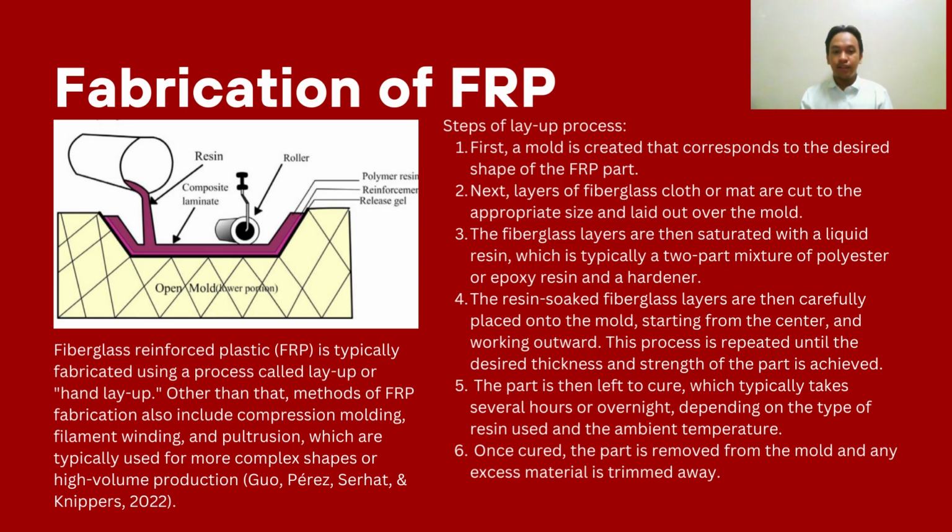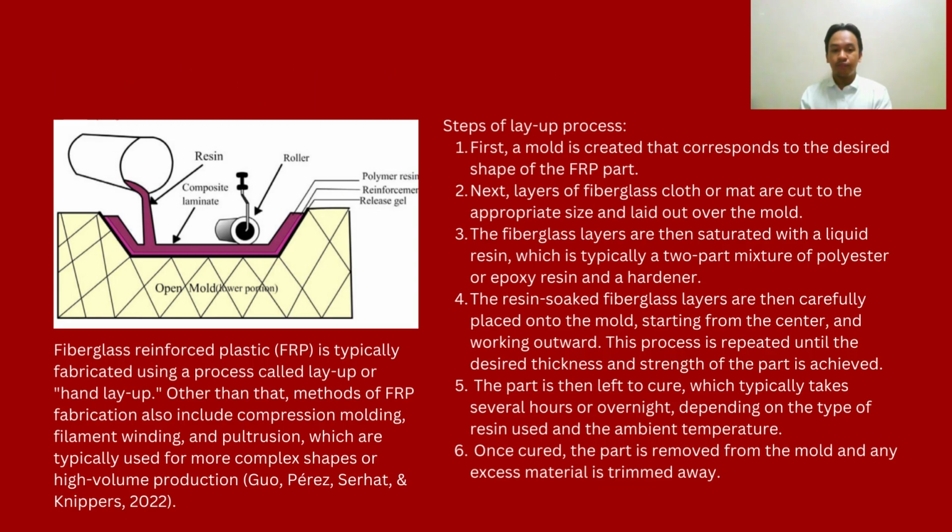The part is then left to cure, which typically takes several hours or overnight, depending on the type of resin used and the ambient temperature. Once cured, the part is removed from the mold and any excess material is trimmed away.